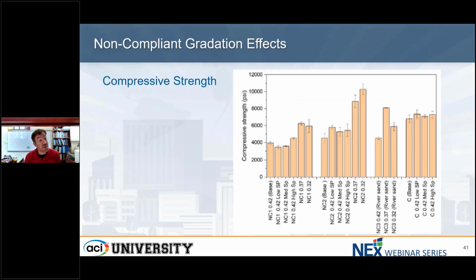And then we look at compressive strength. Now this one was kind of interesting. So we look and see, again, our aggregates that are too fine. Until we get to relatively high dosages of superplasticizer, we're actually not doing so well compared to the identical mix with a compliant aggregate up here. So we may suffer when the aggregate is too fine with our strength.